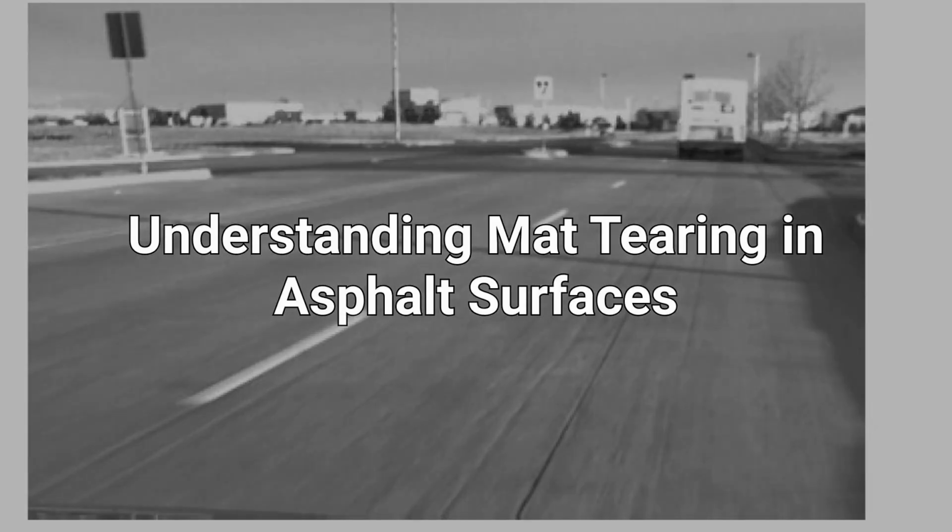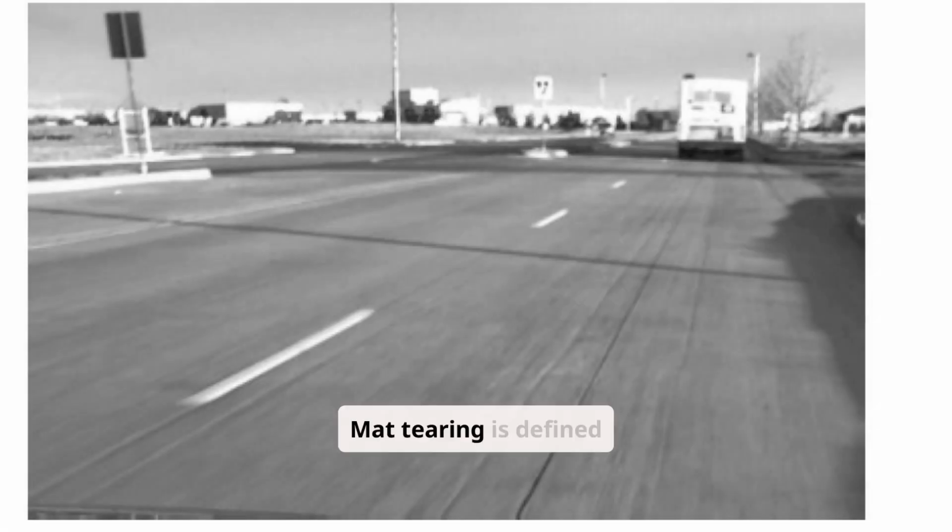Understanding mat tearing in asphalt surfaces. Mat tearing is defined as the surface dragging defects, torn or streaked areas, that occur in the asphalt surface during the laydown and compaction operations. Torn or streaked areas may have higher air voids and are susceptible to decreased stiffness, reduced fatigue life, accelerated aging, decreased durability, rutting, raveling, and moisture damage.